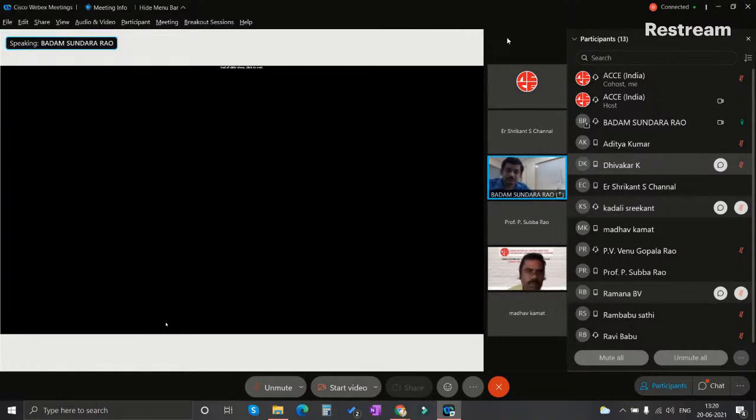And under what situation do you recommend triaxial testing? The triaxial test is the most practical and correct way of testing, as the stress state in the soil is to be assessed first. Suppose saturation is there and the clay is soft to very soft or medium stiff, in saturated conditions. The UCC test, the unconfined compression test, is a simple test that simulates only the axial stress application, that is sigma 1, the major principal stress, and that is more than sufficient.